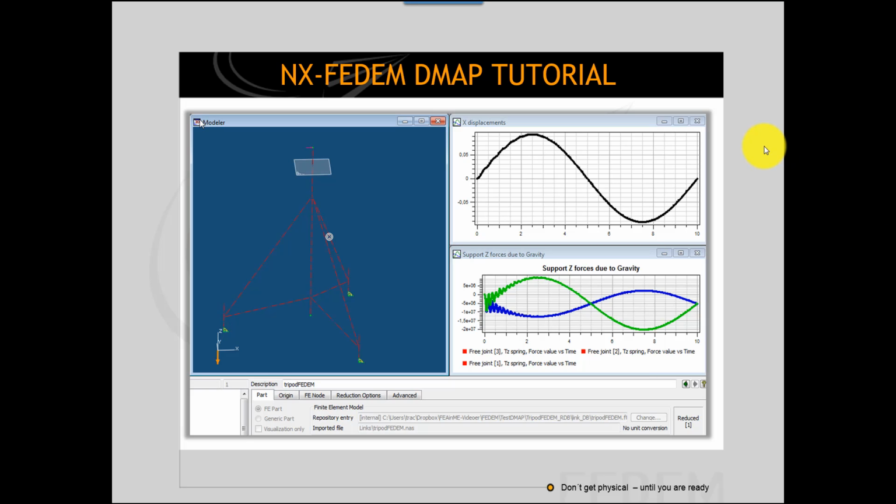You might not know that all solvers in Nastran are based on DMAPs, and you can also alter these DMAPs. You can compile them with the list option, and then you can see the contents of those routines, and you can then add your own stuff in there in order to alter the execution and create your own solver.